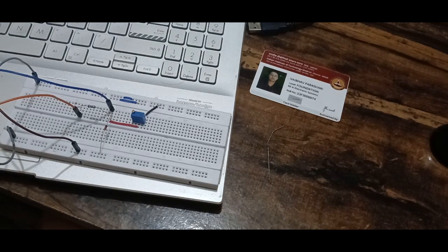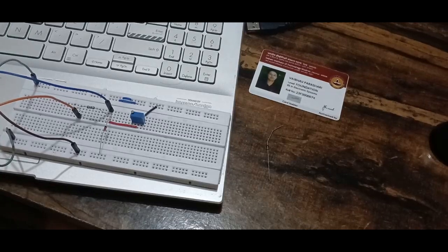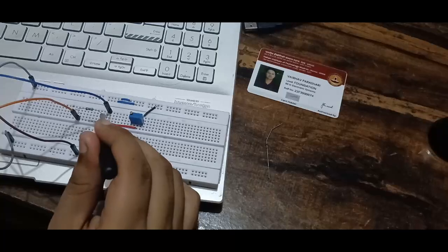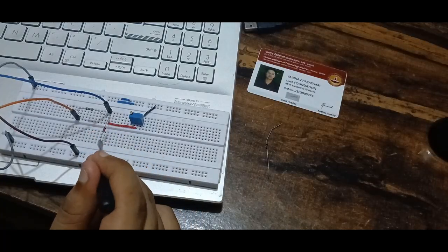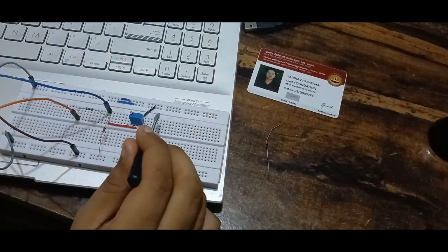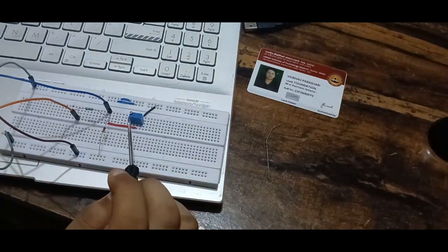So in part 2, which is our experimental study, I set up the circuit according to the figure. This is our 220 ohm resistor, connected in series to a Zener diode, and there is a pot. The connection goes to the second pin, and our third pin is grounded. The pot here works as a load resistance.